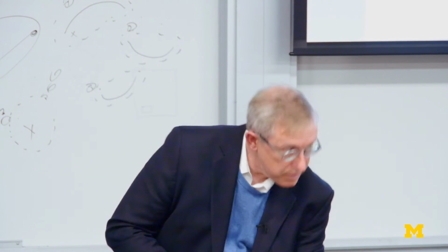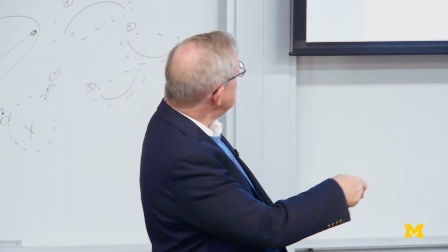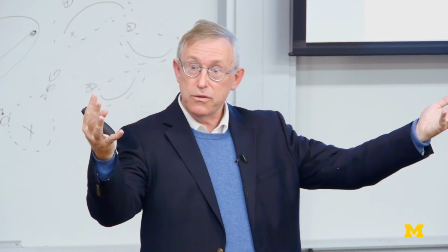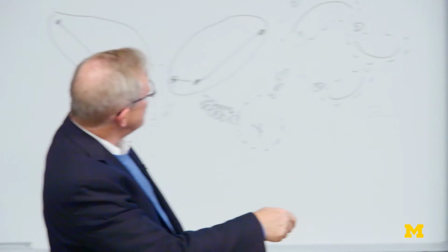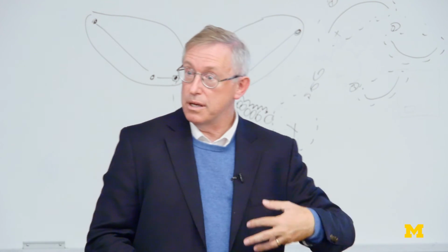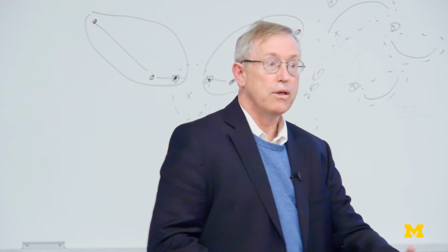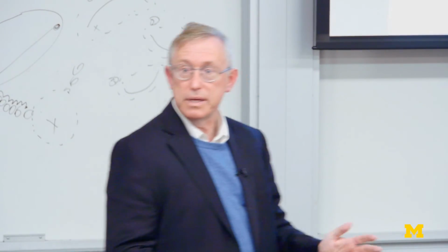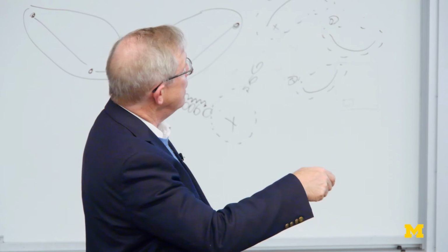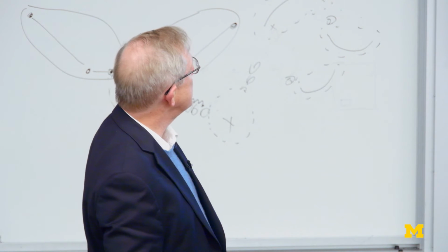We're looking at the channel of interest in a WDM, and we're increasing the power of every user in the system simultaneously. It's exactly the nonlinearity that's causing extra induced interference noise to come into play. So at high launch power, we're getting much more interference noise coming into the system, and that's causing the signal to drop like this.